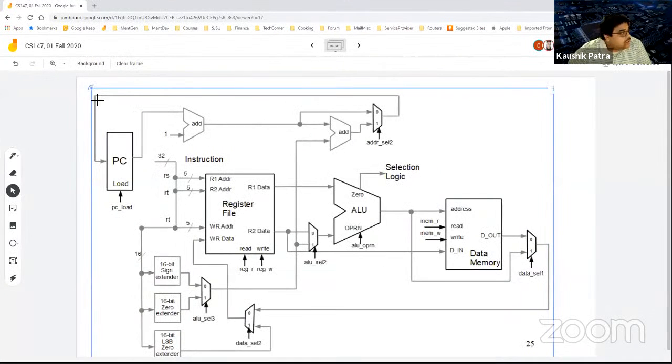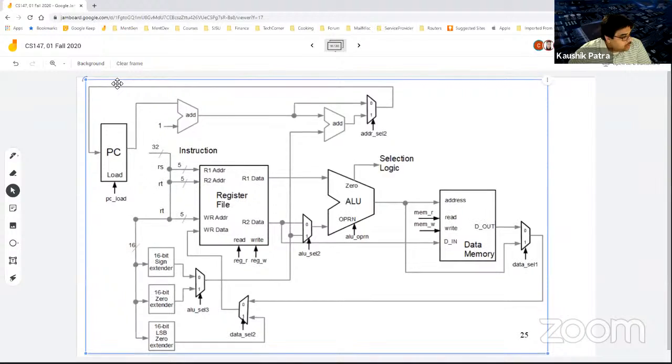And now the question becomes: we have all these different control signals, and a lot of multiplexers came into the picture. So we need to make sure that we hold on to this multiplexer control signal, especially for the data selection or operand selection for the ALU, from the beginning of the EXE till it is written back.